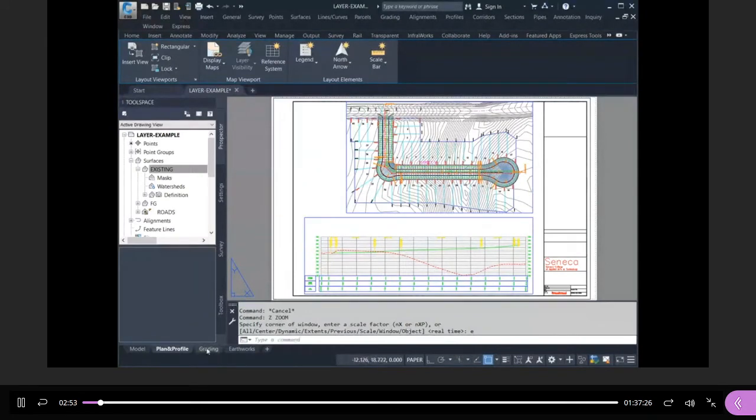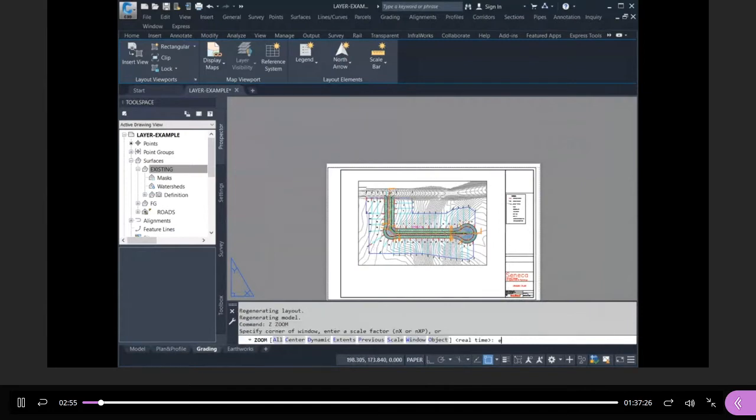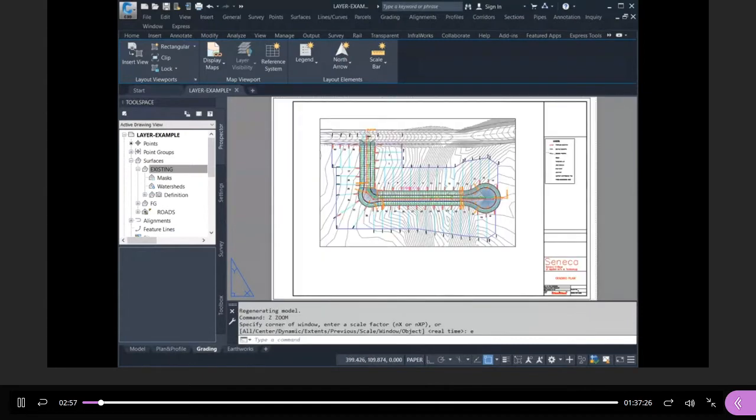When it comes to the grading plan, the purpose of the grading plan is to do the earthworks. So they actually move earth based on this elevation plan, right? The proposed elevation versus existing. So in this drawing, they want to see all the surface features, right? So imagine you're walking on the actual ground. What would you see and what wouldn't you see? And basically, you would see any information related to the surface. Anything underground would not show.